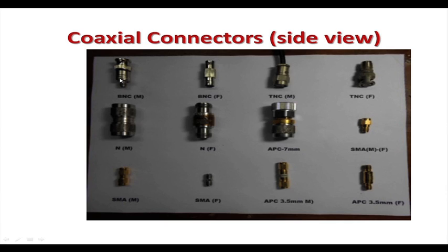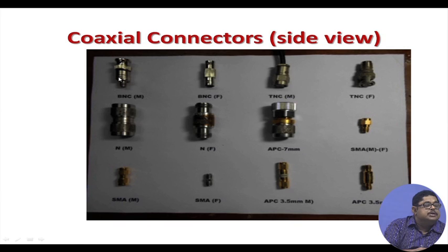So already you are familiar with this BNC. In most of the oscilloscopes, megahertz oscilloscopes, you use it. Also in microwave lab, in the VSWR meter you have this BNC, it has a slot. So, when you put it, you will have to match that slot so that it gets fitted there. So, it is a coaxial connector, but this is not a microwave connector, it is generally in the megahertz range people use it.